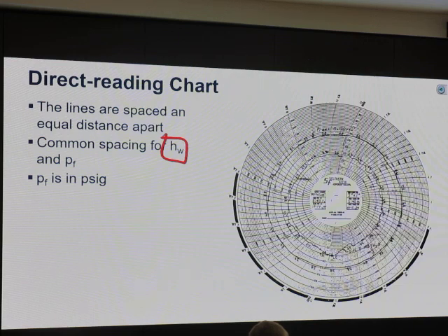So the pressure drop will be 20 to 80 inches of water. We want the pressure drop to be between 20 and 80 inches of water, or 20 to 80% of the reading. If we have a different chart, it may have a different range of the reading. So for the meter to work properly, the signal should be between 20 and 80 percent of the reading.